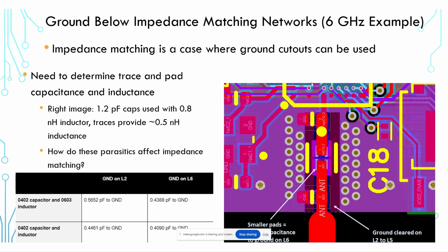However, this component on its RF pin has an output impedance of something like 30 plus 30j, so it basically has 30 ohms worth of reactance. Not all RF components operating in the Wi-Fi range are like that. But one thing I've noticed with a lot of these microcontrollers operating at the 2.4 gigahertz range, or at 5 gigahertz or 6 gigahertz to target things like Bluetooth and Wi-Fi, is the chips are designed such that they have this output impedance of something like 30 ohms resistance and 30 ohms reactance.